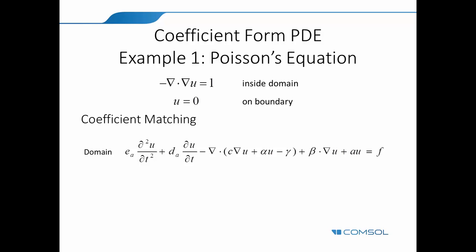So how it is handled is, if you don't non-dimensionalize, in the solver sequence you pick a scaling for your independent variable. So you can specify how it should scale. It will actually divide the error by the scaling you provide when it calculates the error before it puts it into a tolerance. Then I don't need to change my equation, right? No. Just use all of them with dimensions. It's okay. Yes, you have dimensions, and then in the convergence check you would put a scaling. Okay. Does that answer the question?